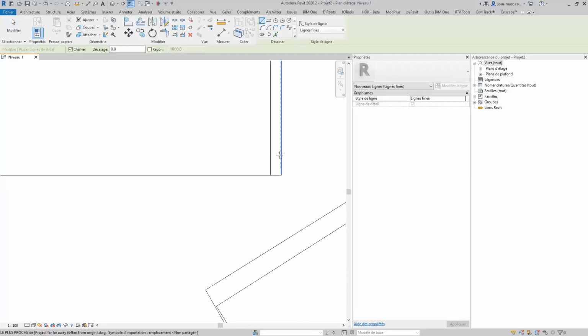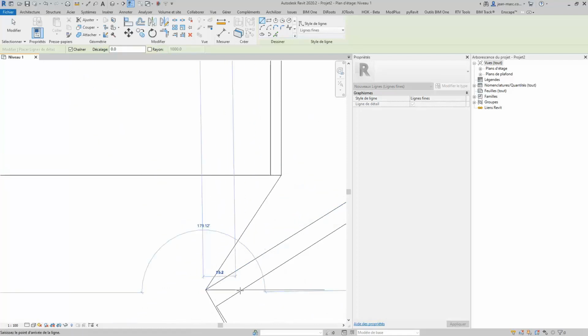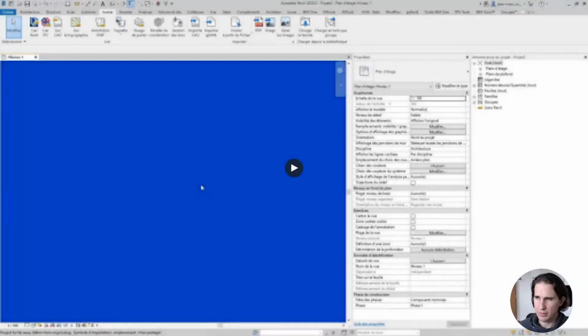You cannot recognize the thickness of the wall, and it's pretty hard to snap properly on the corners without knowing what the problem is. So this issue is mostly due to the floating point precision of numbers, and that implies that whenever you're going over that limit, the lines will start dancing.